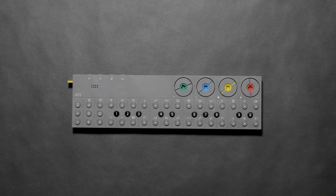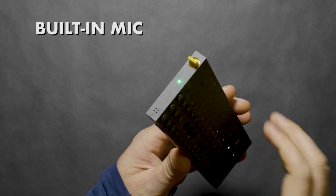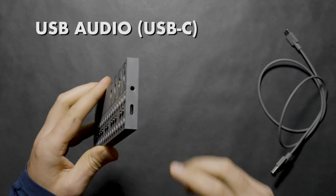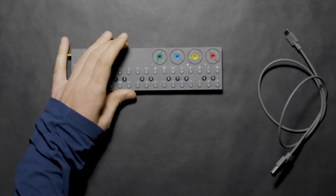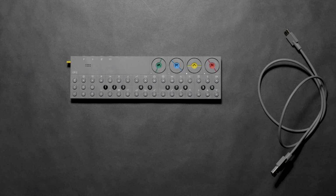This would be a great time to talk about input sources of the sampler. The sources are the built-in mic, the mic input over the TRRS 1/8" input, and the ability to use USB audio. Using the USB connectivity would mean connecting to a computer or phone and setting the OPZ as an audio interface. Since this is the most useful way to sample on the OPZ, we should look at this more closely.